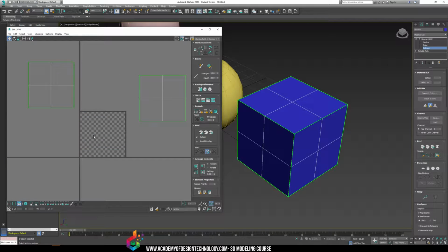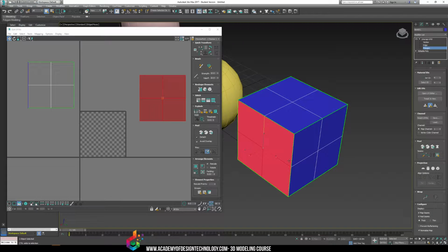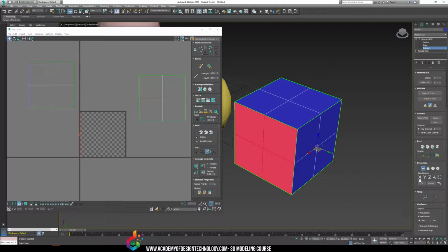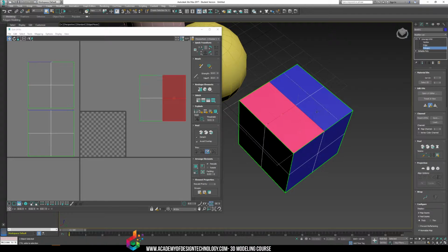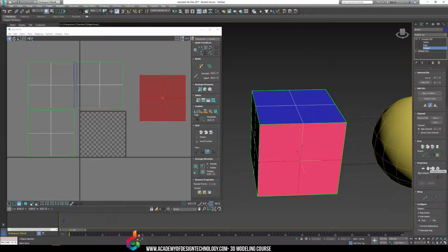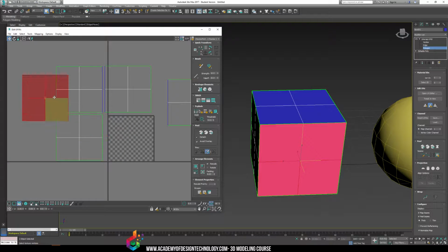And I have that here. I can do the same for all the other sides now. Because it's a very flat surface, I can use the planar map and unwrap all these sides. And I can always just click on best alignment and do that. So I'm going to do that. So go around your model, and I want you to get used to clicking planar map, best alignment, and grabbing each face like this. And then going best alignment.